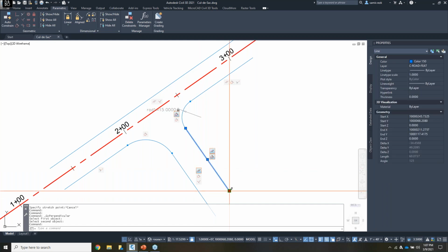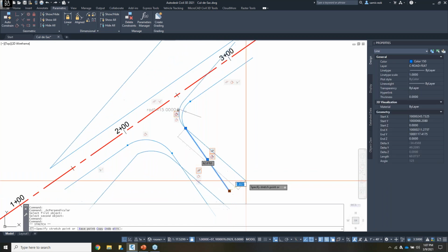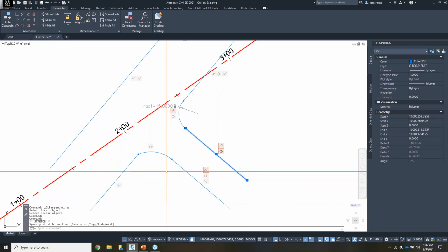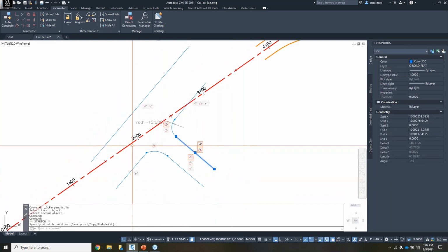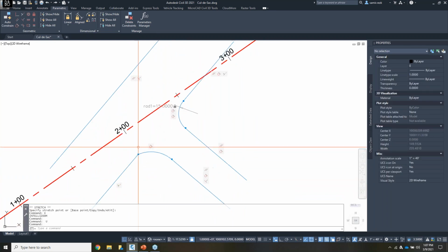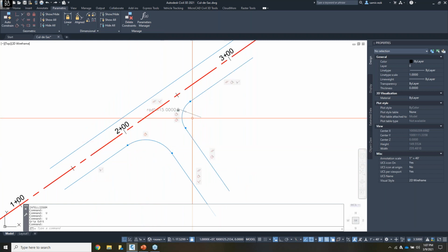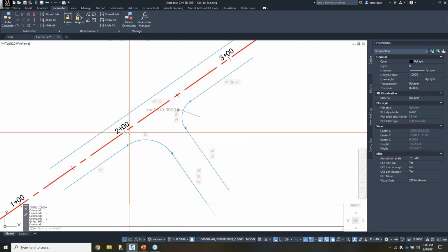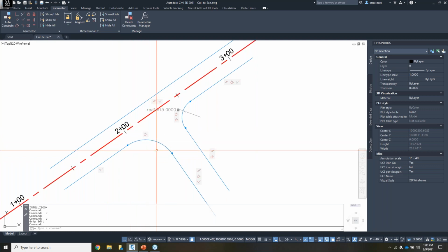So now if this one changes, it maintains its shape. All right, so that's the idea behind constraining the geometry and making the parametric tools work for you. There is a sweet spot though. Not enough constraints, as you can see, and it doesn't hold its shape as much, and too much, you remove a lot of the freedom from each of the geometry.